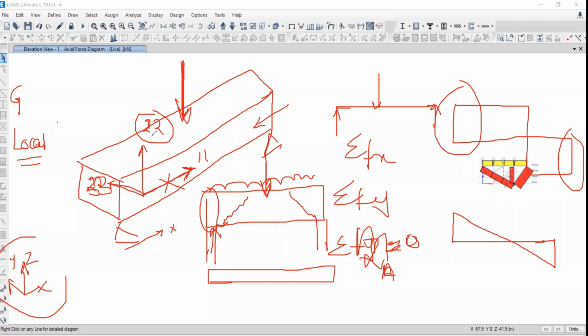Whenever you want to look at how much shear force is coming to your beam, you need to look at axis 2-2. So this is called the major axis for shear. Major axis for shear is 2-2. Minor axis for shear is 3-3. And the third axis, out of the plane, is the axis about which there is a possibility of movement. That is axis 3-3.